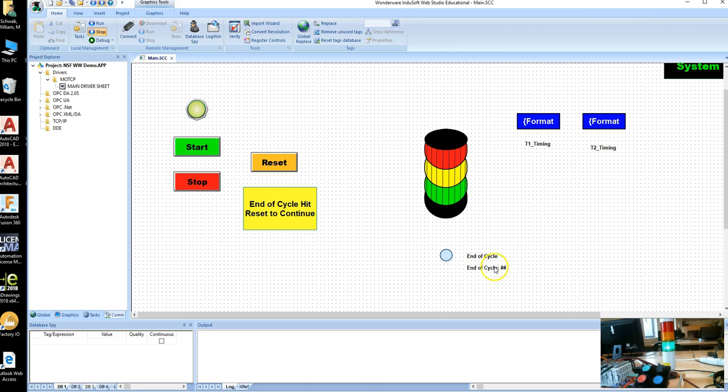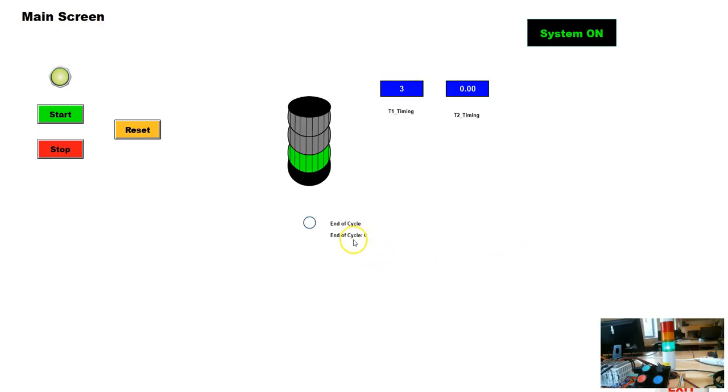But now when I run this, this is going to show me whether it's actually a 1 or a 0. So it's saying it's not active. And a lot of times, like if your program isn't working quite right and you're not sure whether this end of cycle is doing what you think, you can just put that in there and it'll tell you that it's a 0, and you can see it flashed 1. That's a really great troubleshooting technique for when your program isn't working.